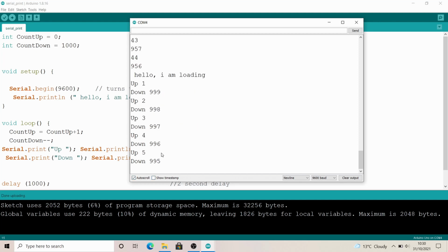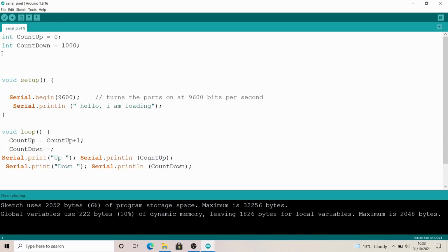One last example for now. Our microcontroller has a basic built-in timer circuit. We cannot use it for reliable date and time, such as hours, minutes and seconds. If the power is removed, it will reset to 0, but we can use it to time events such as how long has it been since a button was pressed.